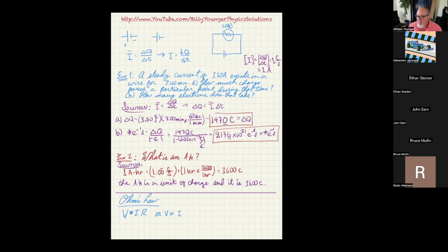Of course, they have limitations. If you put too much current through one of them, it'll sort of explode or burn up or melt or something like that. So they're not ohmic in the sense that it's always going to say the same R is 100 kilo ohms. It's ohmic in the sense that we have a very well-defined amount of power that the resistance can do or can make, while it still remains a constant source of resistance. If you exceed that power, which most of the resistors you are using in your lab are like 1/4 of a watt, 0.25 watts.